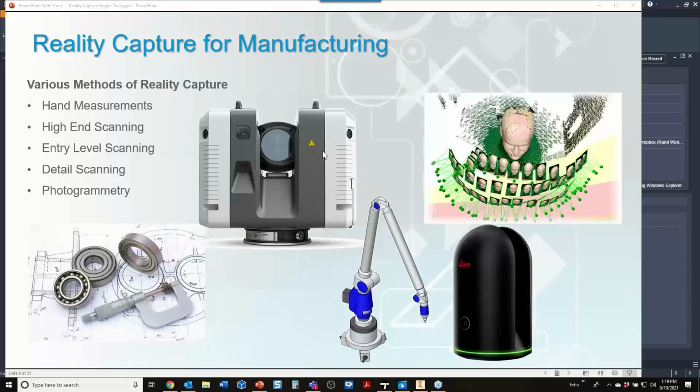But again, I think you'll get a more efficient result if you take a high-end laser scanner out there and you measure everything to within a 1/16 or an 1/8 of an inch. And you know that basically you're taking the reality of a space back to the office with you and beginning all of your analysis with the confidence that all of your simulations are going to be based on the reality of a particular space. But I mentioned also photogrammetry.